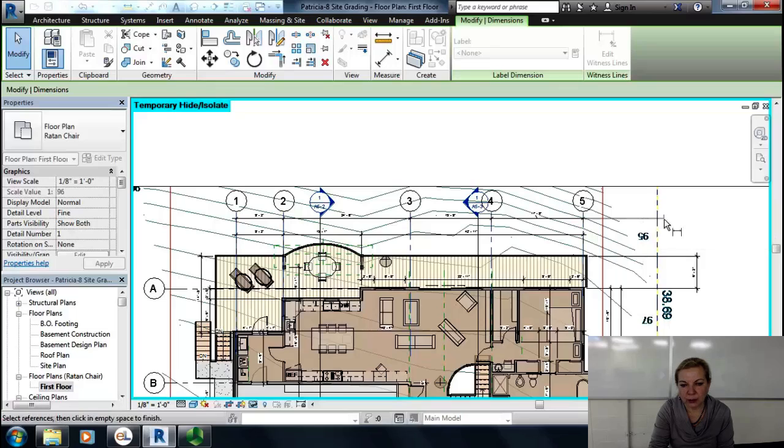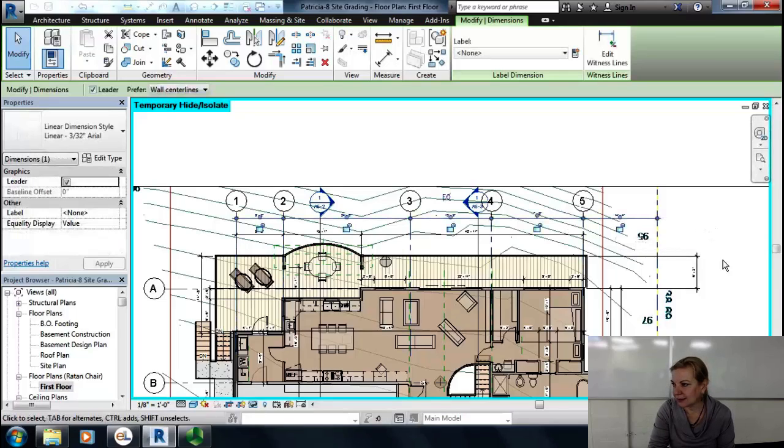So if you forgot to locate the grid line from the property line, you just click on it, and then remember again, no escape, no enter, the whole thing will disappear. Click on the outside. We've added a line. The next thing, to subtract the line, while it's still selected, go close with your mouse to the dimension that you want to select. So let's say that one, I'll change my mind. I'm not going to do it here. I'll do it somewhere else.